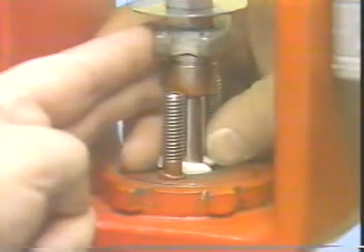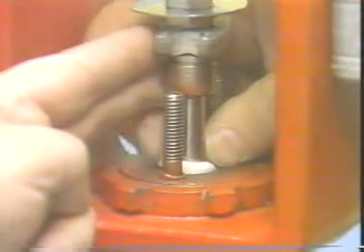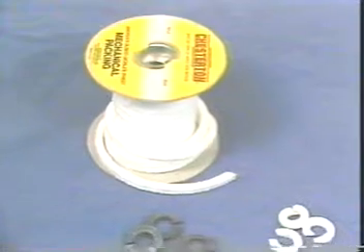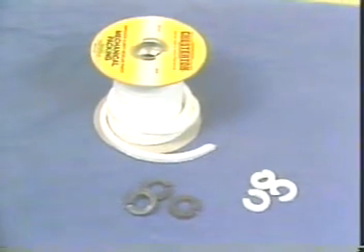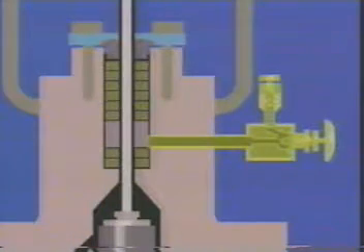Also, many of these materials are suitable for use in high-temperature applications. One problem is the friction between these materials and the valve stem. As you may recall, friction between moving parts of a control valve will result in a degradation of control. To help minimize this problem, additives such as Teflon, mica, and graphite are used. Even with these additives, some braided materials require an external source of lubricant.